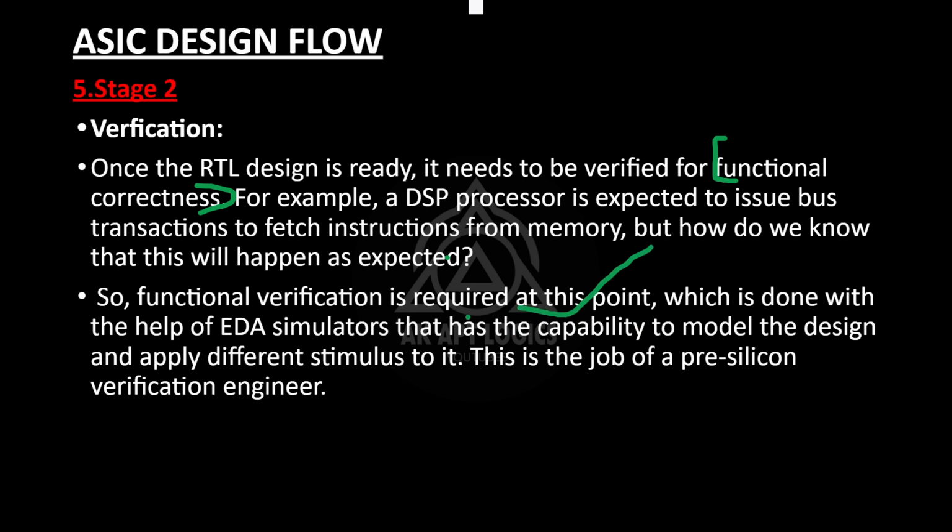This is done with the help of a simulator. There are so many simulators which give waveforms and console output, and they have the capability to model the design and apply different stimulus. Stimulus in the sense of different input combinations, vectors or scalars, different input cases. This is the job of a pre-silicon verification engineer.